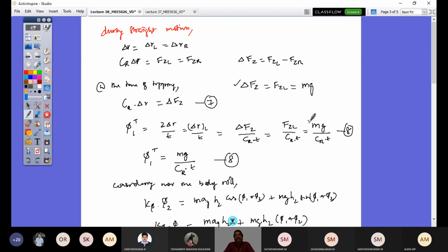So you have seen there is a second term of understeer gradient getting added to my bicycle model, and that is due to lateral load transfer. There are two mechanisms. One is load transfer due to transfer of lateral force to the roll center in the axle. That's an instantaneous effect which is independent of the roll of the vehicle body. Another effect is the vehicle body roll itself. That's what we have seen in the first part of suspension design.